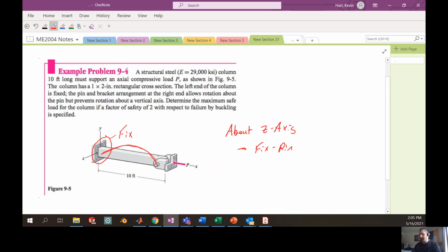Now, when it comes to buckling, you can buckle not just about one axis, you could also buckle about the second axis. And in this case, we could have buckling about this other direction, which would be a buckling about the y-axis, which, if you're just holding a ruler in your hand and not considering boundary conditions, would be the direction that you would expect it to bend in this situation, which is this buckling mode right here, coming into and out of the z direction in this way.